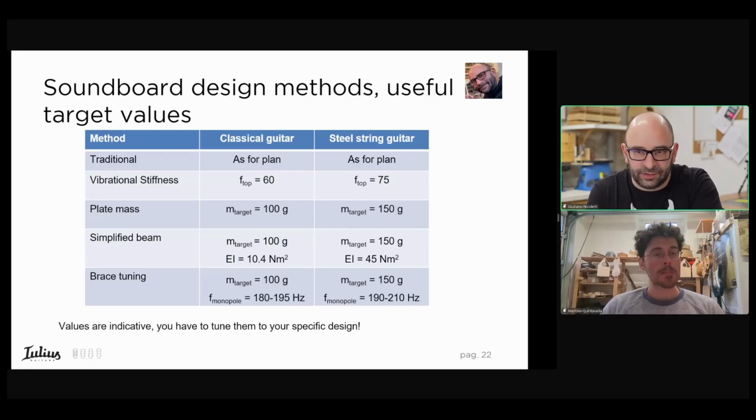In the book, I also simulated the difference between a flat and a different arch of the soundboard, and this mainly affects the monopole. It is also intuitive because the monopole is the only resonance that affects the whole surface of the soundboard, and arching has very little influence on the frequency of higher order modes. So no, we didn't take this into consideration, but the geometry is the same for all the models, and the boundary condition we already talked about is a fixed constraint.